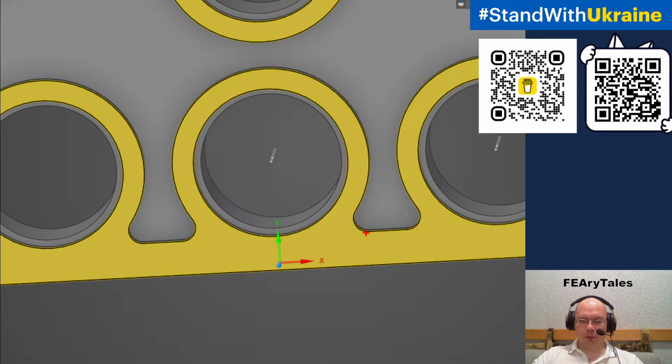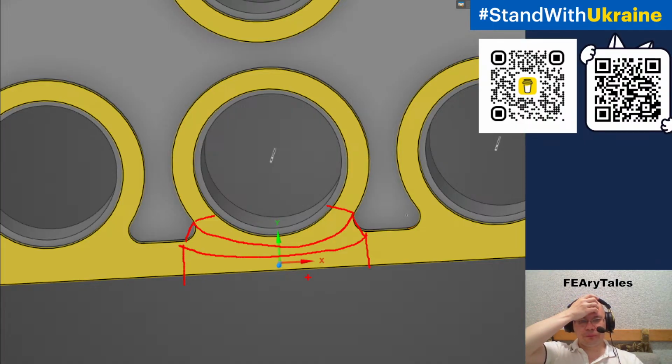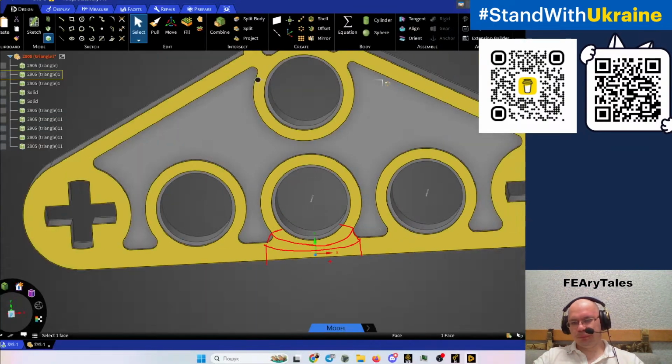You can split these big faces and these small faces into smaller objects. Every one of these objects can be split in such a way as to obtain a fully hexa mesh without any sort of complex geometry, only with hexa volume.